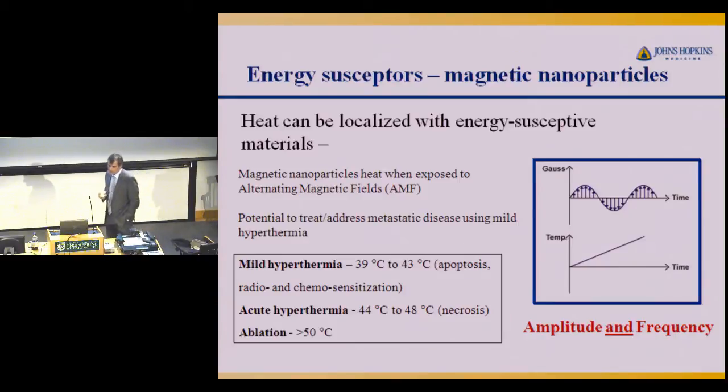And so now another slide, courtesy of Alan Foreman, we can localize the energy to convert to heat with magnetic particles because of the unique interaction that AC magnetic fields have with materials. There are basically a couple of modes of interaction. One is through hysteresis in magnetic materials that generates heat. Another one is through induction.